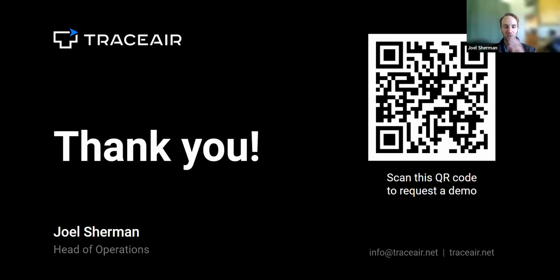There are cases where that is true, and yes, we would go to that technology at that point. But for the 99%, we're not leveraging that type of laser. We're leveraging a laser that travels well through air, but not through water. So when it hits a water surface, it will deflect off and not give accurate measurements from the bathymetric surface, or the bottom of the pond.